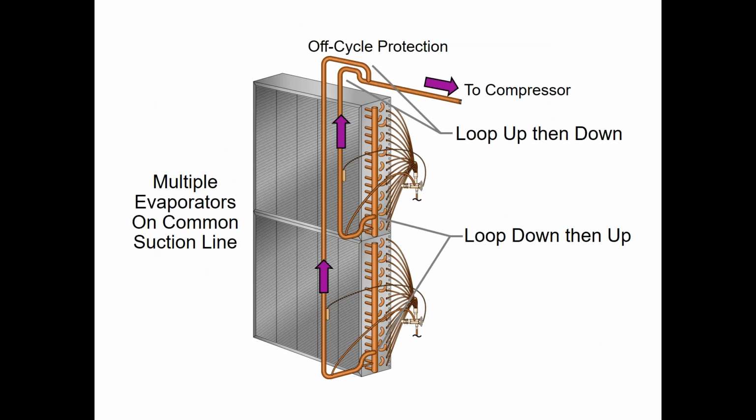So let's talk about the evaporator and manifolding of evaporator coils. A couple things with DX cooling, especially when you get into VAV or VVT applications. Any kind of variable air volume or temperature applications, we have to have what's called full face active coils. So here we have an upper coil and a lower coil. By full face, that means both coils need to be active during operation.